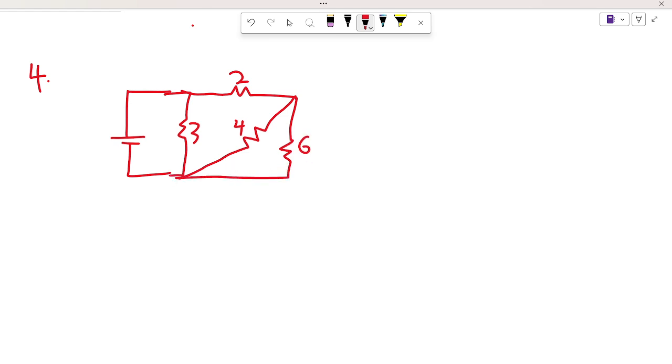First of all, we check for our effective circuit, and both possible passage places for the current have resistances, and throughout there are no short circuits present, so we can move on. We are going to start simplifying from the right hand side, that's this point. We realize that the 6 ohm resistor and the 4 ohm resistor are in parallel.